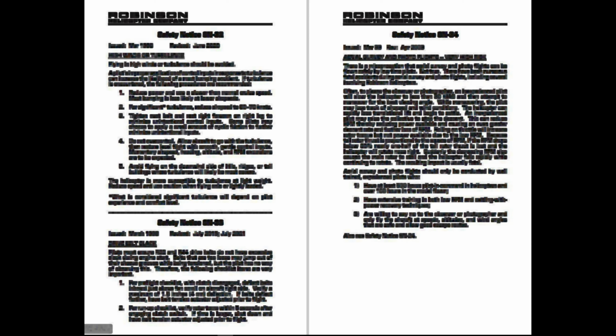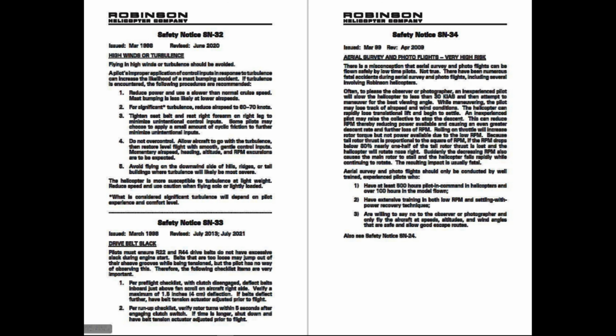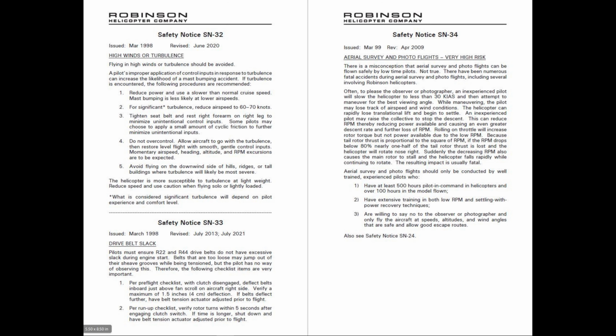Can the aircraft fly with luggage or cargo stowed on the landing skids? No, the landing gear are not designed to take downward weight. They're only meant to take upward weight, even for hard landings. An object stowed on the landing skids might cause vibration that could cause damage to the airframe.